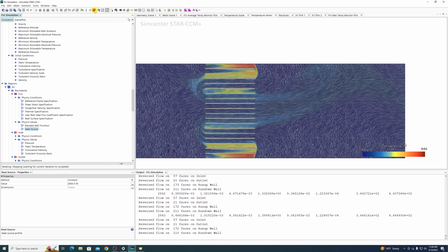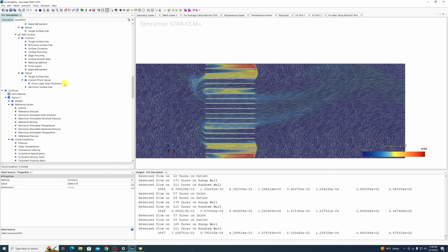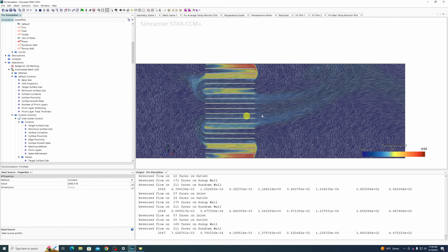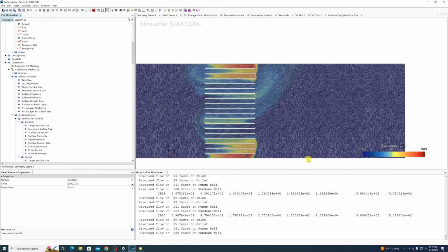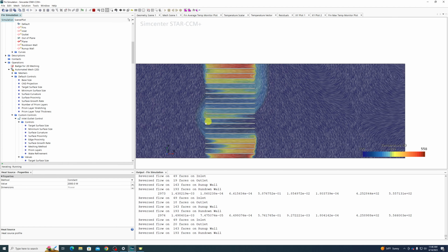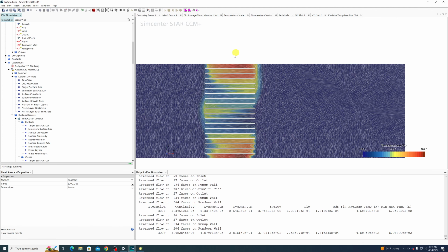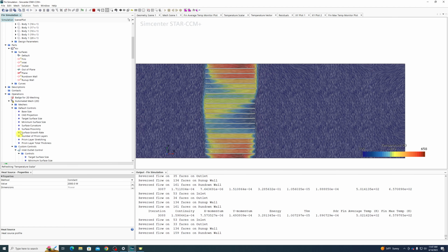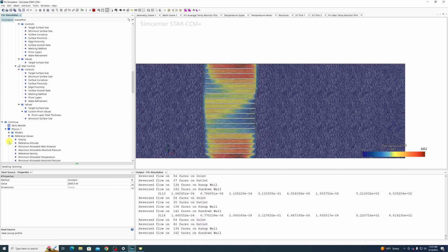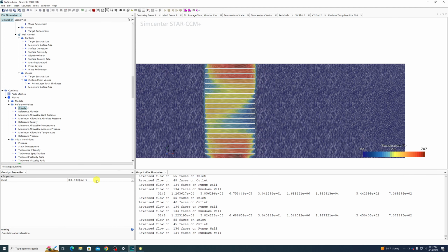Ooh, actually, better yet, we could change the direction of gravity. Right now, gravity's up and down, so clearly this is going to be rather unstable, right? Because air is trying to interact with perfectly horizontal plates. It's working on it, but it's having a hard time figuring out how to do this. It's kind of doing this zigzag path through these plates. Let's go up and take a look at gravity and change the gravity direction.